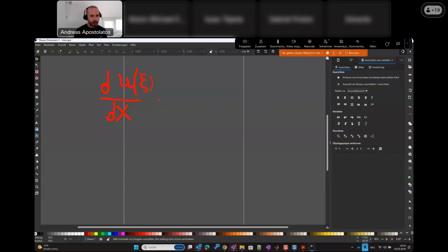So here we have basically, let me just type it, du over d psi, and then we have d psi over dx. Exactly. So what is this here? And that's, Gabriel, the so-called inverse of the Jacobian.